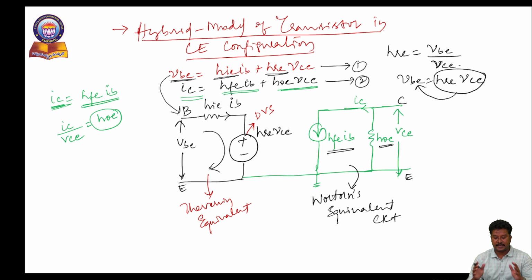Generally, a transistor is a non-linear device, but by considering the transistor as a two-port network, we convert the internal behavior of a transistor into linear elements. It is one of the important steps we consider. Once everything is defined in the form of linear elements, it is more convenient for us, as from electrostatics and circuit theory, once you convert it to an equivalent model.